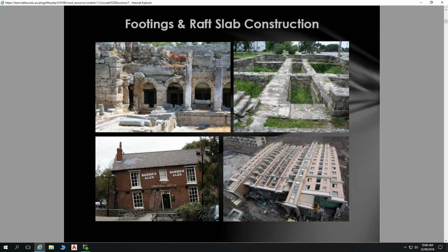But let's say I look at this light track up here. That's suspended from these cables like that. It's hanging down. In between the suspension of those two cables, the base of that light support is going to be in tension. The top of it is going to be in compression. As it wants to deflect like this, the material at the top gets squashed together, the material at the bottom gets pulled apart.